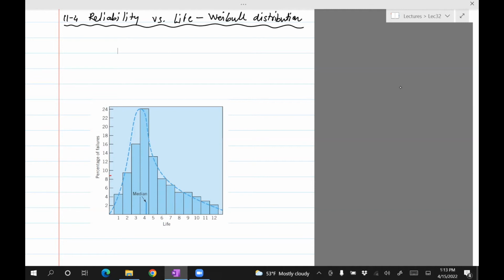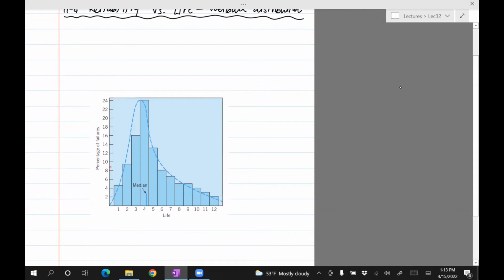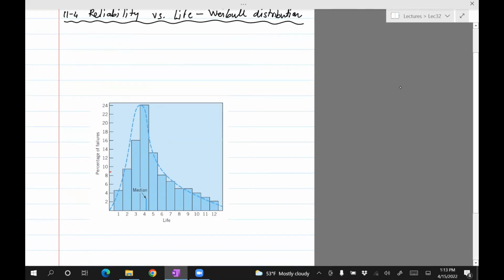And what this figure shows is pretty much that. When you study the failure and make a plot based on experimental data, you'll see that there is a peak like this. This is basically where a big percentage, in this case 1/4 or 25% of the bearings, will fail at about 1/3 of the life of the bearing.